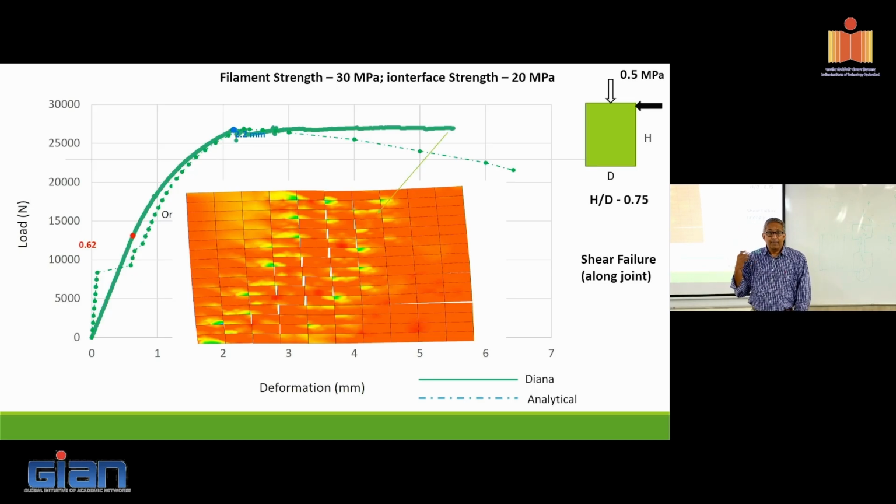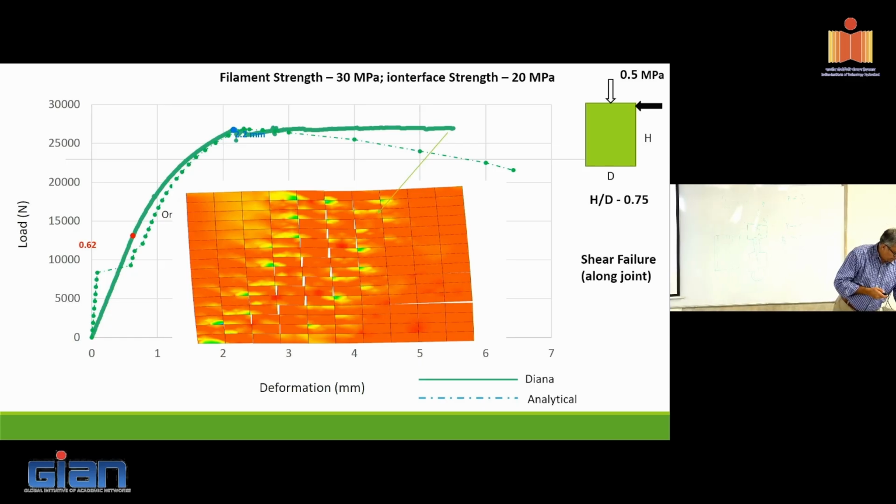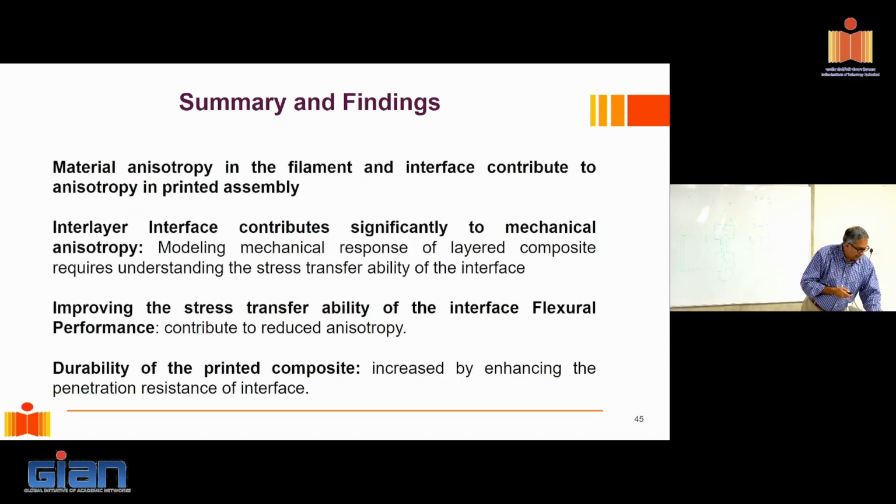Okay, so in my opinion, if we are really to get into the next scale, start designing, we really have to start paying attention to this, start characterizing the interface properly. When I say characterizing, I don't mean the microstructure characterization. I mean, how is it behaving under different stress states, right? And then we can calibrate a model like this. And if you give me a 3D printed wall, I can give you the predicted response.